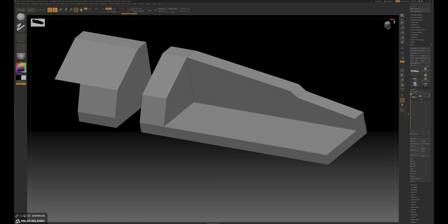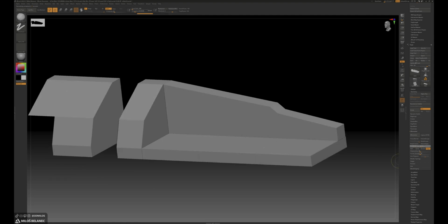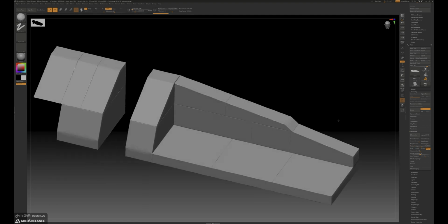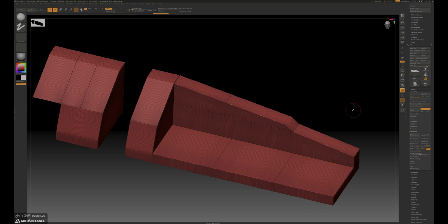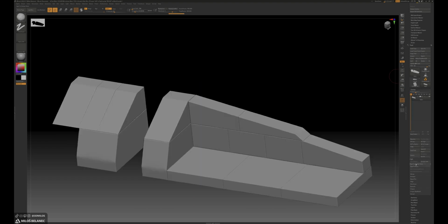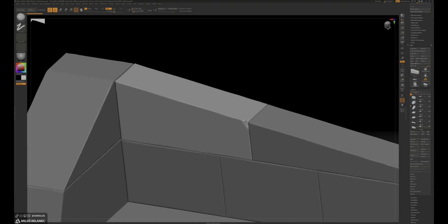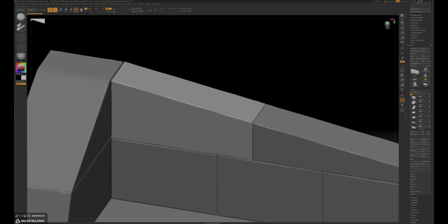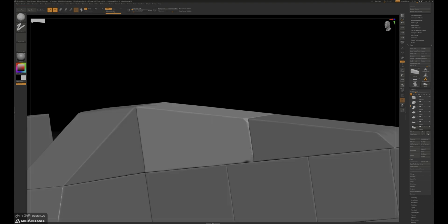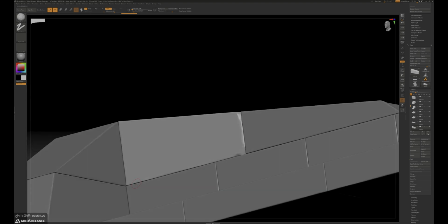Okay, let's start with ZBrush, one of the most important tools in this pipeline. And yeah, we have this model, but the density of the model is not good for sculpting. We can use ZRemesher, the density will be better, and we can start sculpting on the edges. But before that, we need to split this model into separated parts in the subtool menu. After that, you can get better control around the object. You can hide useless models in the scene.